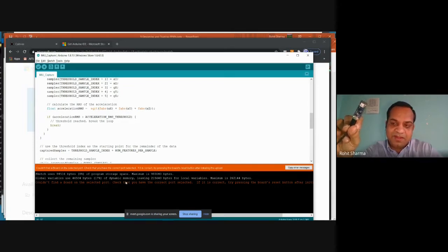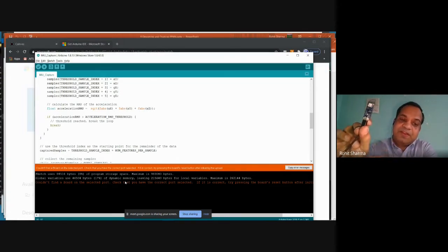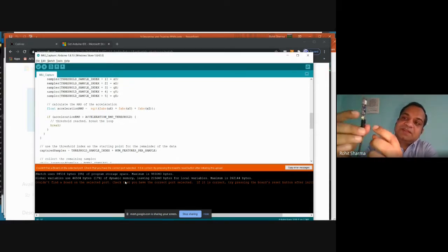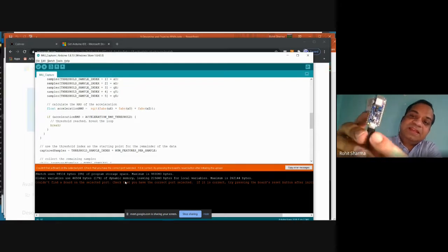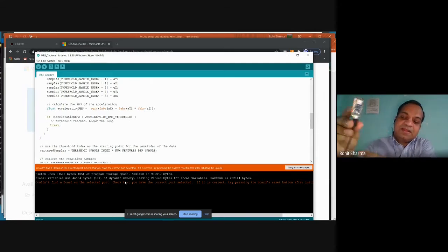This is normal, and the reason is you see this yellow light that might have come up recently after the compilation and when it starts to upload. So right now at this point, this is in the bootloader mode, and you have to press this tiny reset button that is barely visible. If you press that, then you would hear the sound, and then you can disregard this notice.